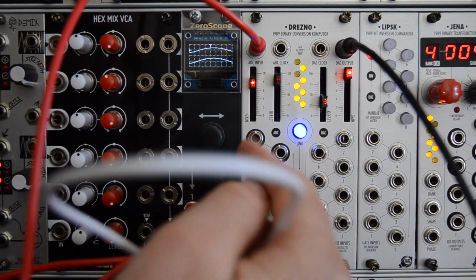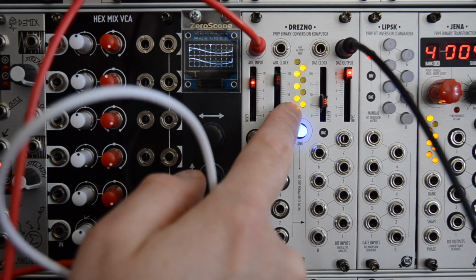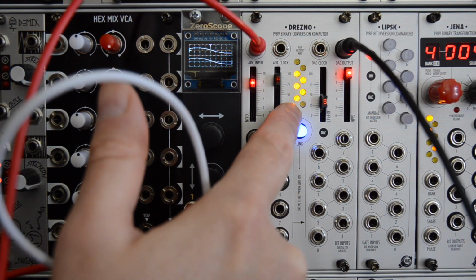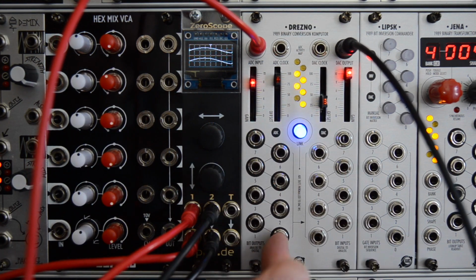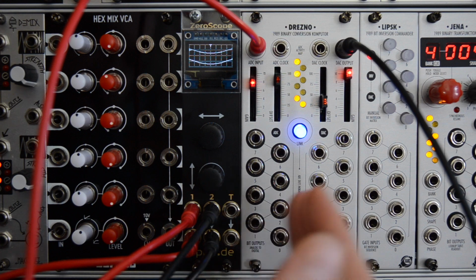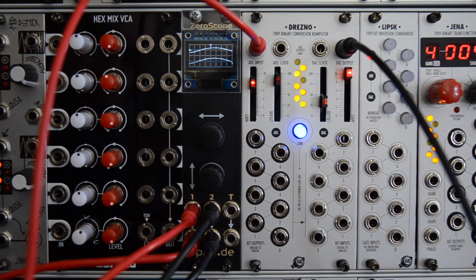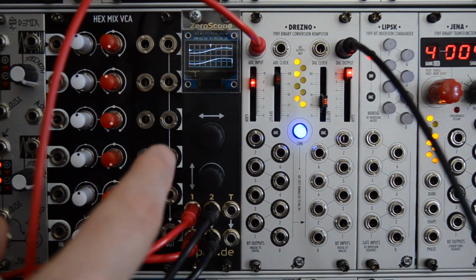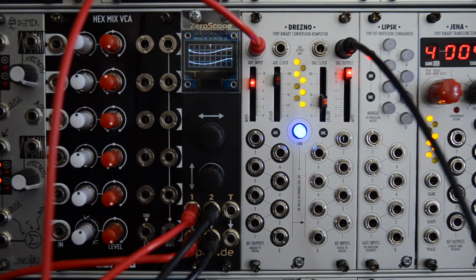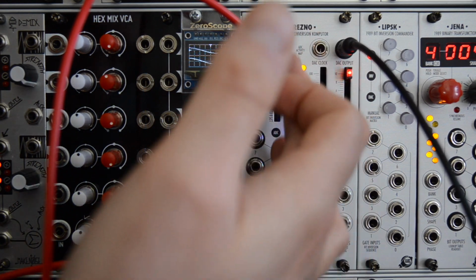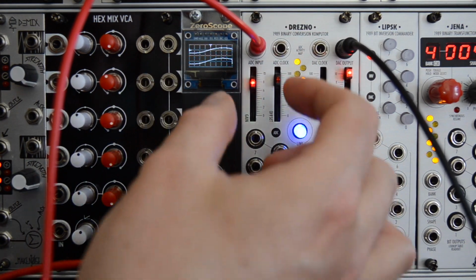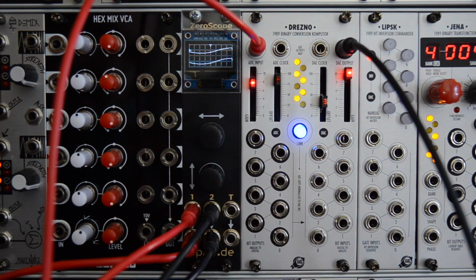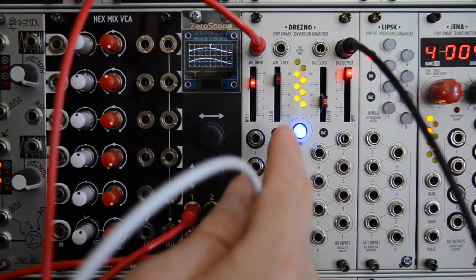And now you can see that the bottom bits, being the least significant ones, are indeed the ones that change the fastest, but they will inflict the least change in the output of the wave. And the top bits, being the most significant ones, are changing really slowly. And by the way, these LEDs represent the binary numbers in the input stage. You'll see, for example, 4-bit 4, which is this one.